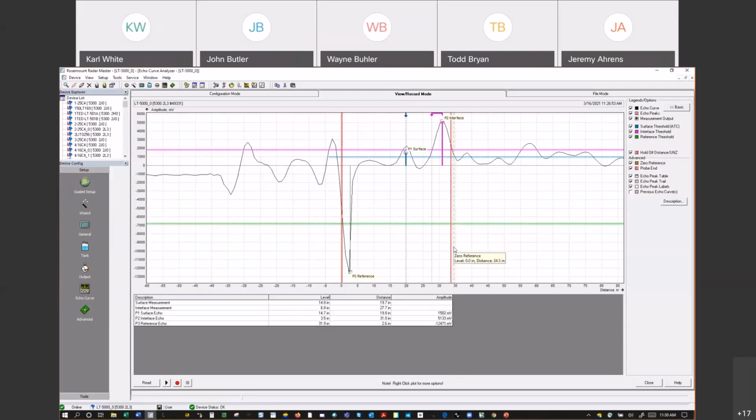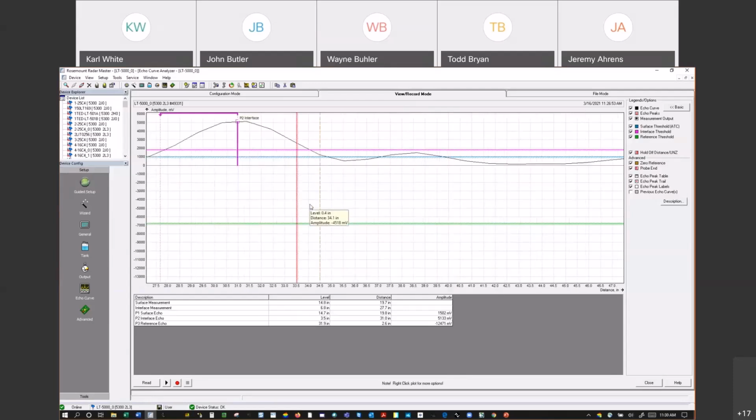If you put the tank height 6 inches lower, which is pretty common, we normally say put the weight half an inch off the bottom of the tank. The weight is like 5.5 inches tall, so that's 6 inches, right? So if you put the probe length to the top of the weight, which is 6 inches above the bottom of the tank, interface goes to 0, which it should be 0, it'll actually show 6, and that's because it's reading the top of the weight.